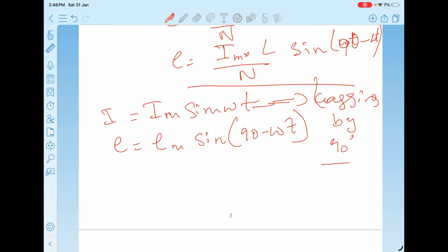E = L di/dt is the voltage across the inductor formula, and to have this induced EMF you need a change in current. For a DC voltage source, this di/dt will be 0. So induced EMF will be 0 for DC voltages. That means there will be no opposition. So if you connect a DC voltage source to an inductor, the opposition will always be 0.